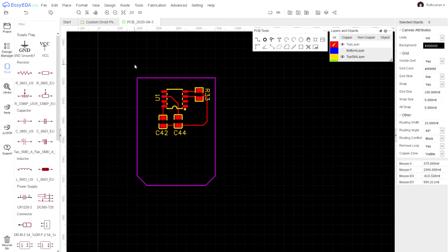For example, the pads for the footprint, I should say, that we're using right now is for a very small, 150 mil package memory chip. I want to extend the footprint, those pads for the pins. I want to make them wider so that this PCB design could accommodate larger memory chips.